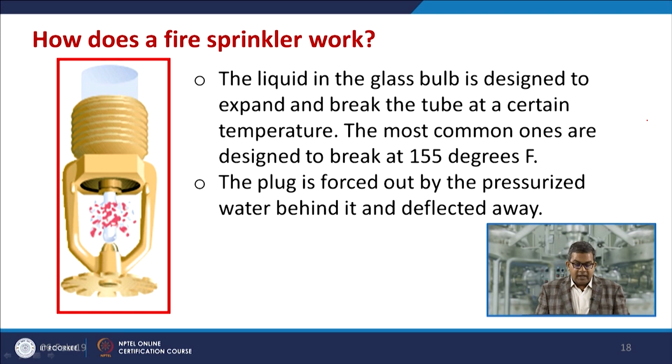The liquid in the glass bulb is designed to expand and break the tube like this. It is broken over here. The tube breaks at a certain temperature. The temperature is specified, but the most common ones are designed to break at 155 degrees Fahrenheit.